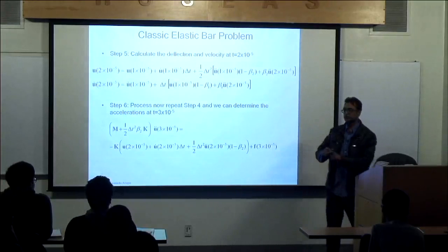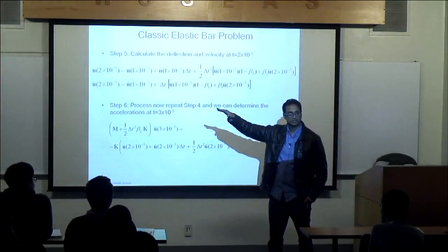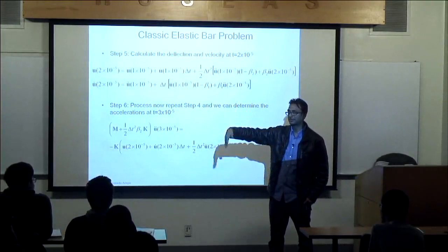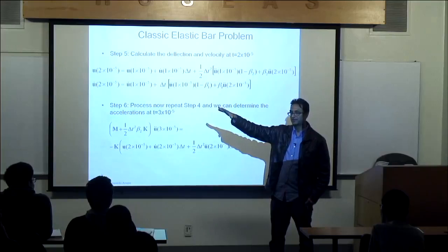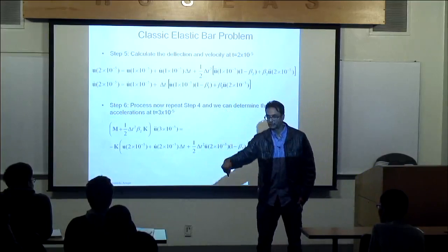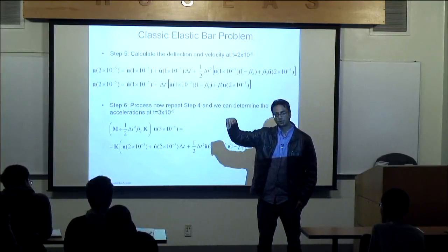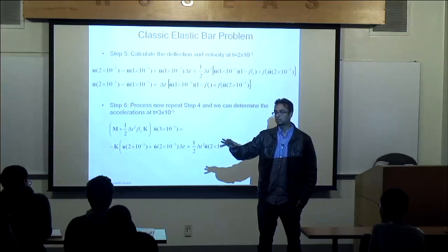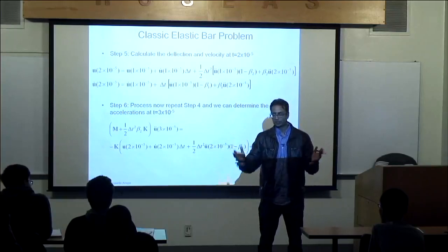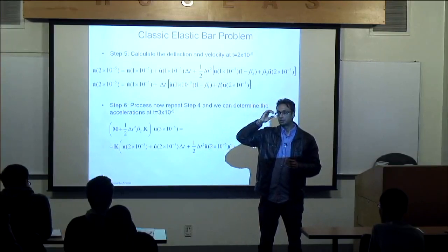Have you seen sometimes those diving boards go bananas? They actually accelerate more than what it should look like. Why? Because if the forcing function of the person, the frequency of that force from that person bending that board, matches the frequency of that beam, the beam is going to accelerate even more. Okay?